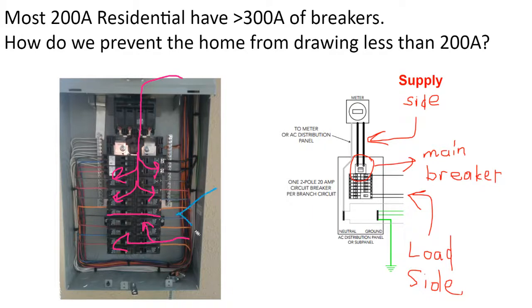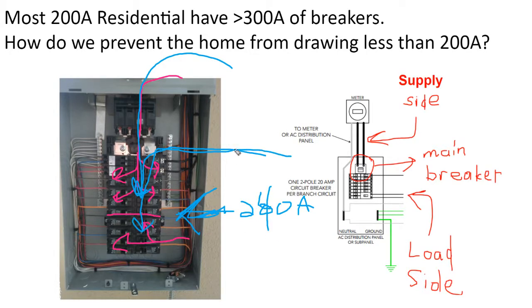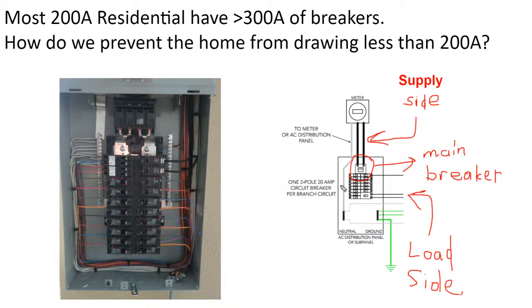If the solar array were landed anywhere else than on the bottom of that service panel, potentially its power supply could combine with the grid to exceed the rating of the bus bar by supplying 120% of the amperage through a cross-sectional area of the bus bar. And so this exception is only made when the two feeders of a panel are located at opposite ends of the bus bar.